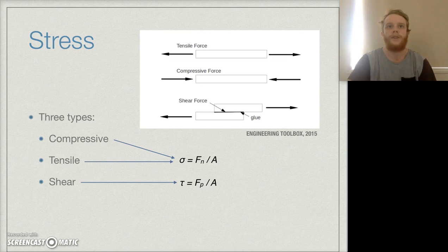Similar to a tensile stress, compressive stress is where the force is applied normal to the face of an object, inwards so as to compress the object. This could be explained by a concrete column which is supporting a balcony. The balcony is applying a force relative to its weight, while at the bottom of the column there is a normal force opposite to the weight. This will tend to compress the column.